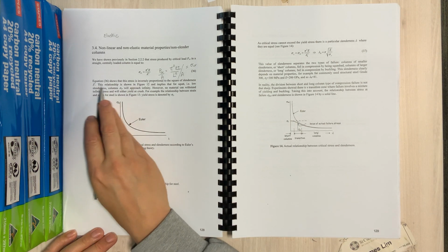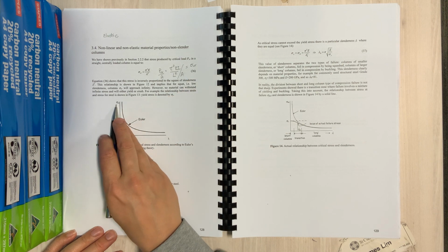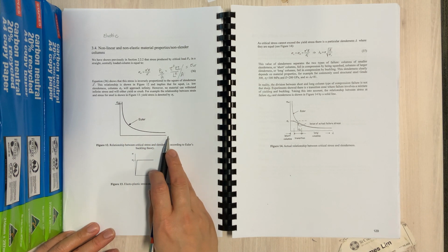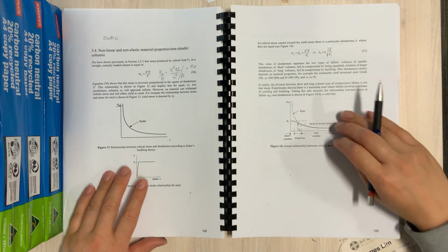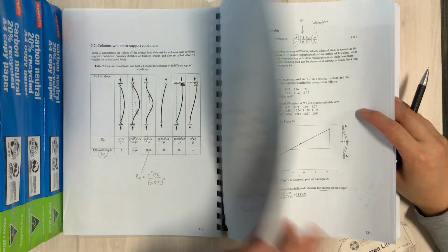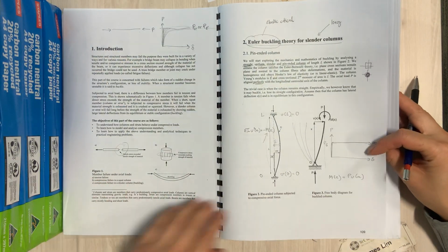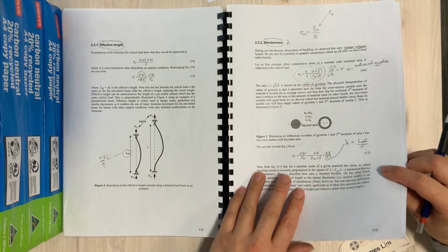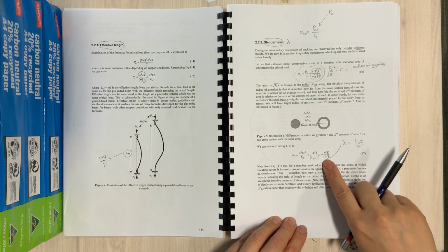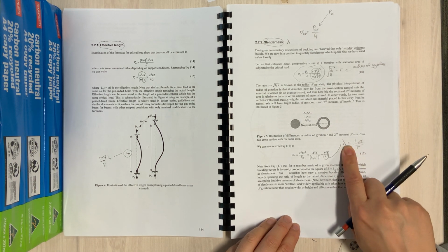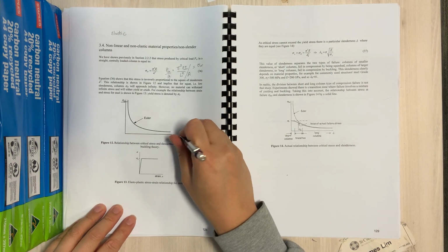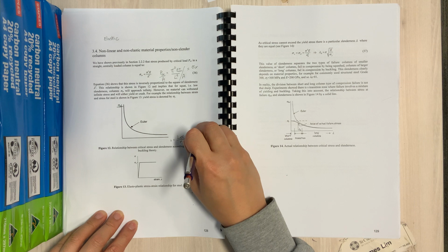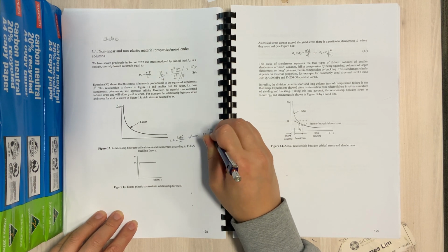So let's now plot this for the elastic critical stress. Here we've got a stress, and we plot that against our parameter lambda, where lambda represents the length. If we flick back through the course book to where lambda was talked about, lambda being our slenderness, just before the mid-semester break, lambda is equal to the effective length over r, so L effective, which for a pin is the same as L, divided by r, where r is equal to the square root of I divided by A.